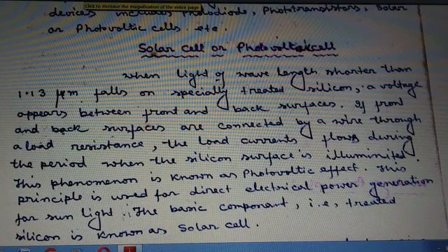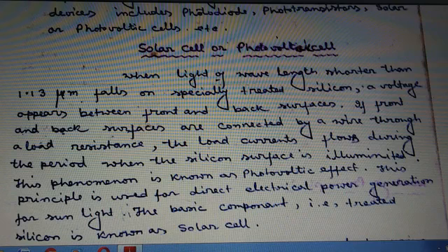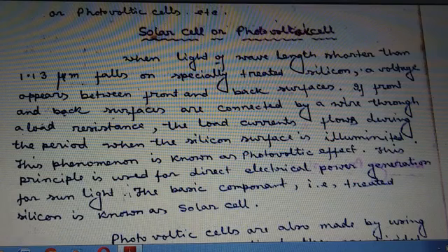The amount of this generated electricity depends upon some factors like the intensity of the solar insolation or radiation, size of the solar cell, types of the semiconductor materials, and the ambient temperature. From one solar cell, only a small fraction of electricity is obtained, so to obtain a considerable amount of electricity, these solar cells are connected in series and parallel combinations, called a solar photovoltaic module.